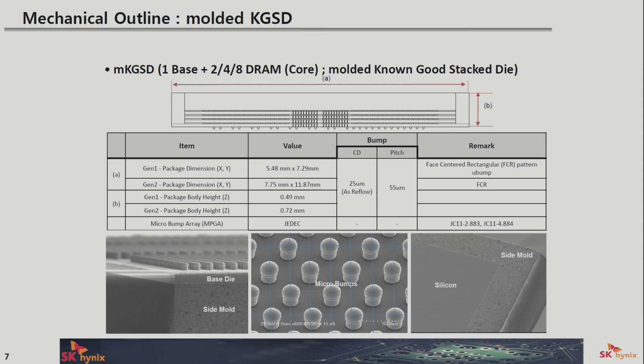So in terms of the mechanical aspect of the HBM device, JEDEC, the standardizing body, has agreed that the Z height will be 720 micron. The XY dimension will vary between DRAM vendors, and this adds a level of complexity in terms of the supply chain for customers adopting the device, because depending on the 2.5D process and also the integration process and the interposer design, customers may have to use different interposer designs for each DRAM vendor.